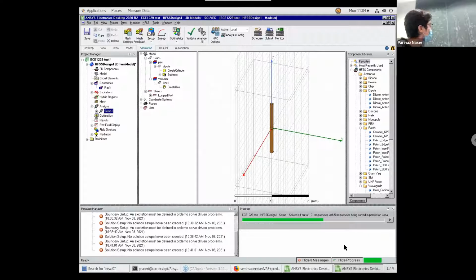Another question is, for example, for this structure, we know after 5 passes we're going to get converged results. The next time, can we directly go to pass 4 and then 5, ignoring the first 3? Yeah, you can. What you can do is assign or initialize the mesh. So you decrease the meshing size, you mean that? Yes, basically that way.